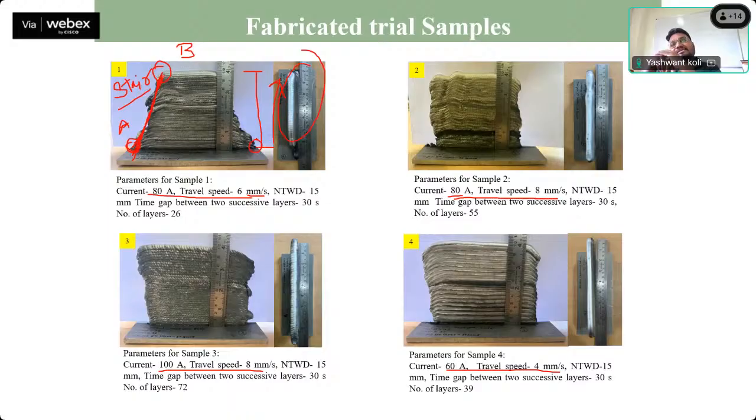This defect can be removed by correcting the dimensional accuracies, at what position the arcing has to be started and the arcing has to be stopped. That consideration we have to take care of. So it should not be like this. This has some staircase defect, you can see, but the undulations are not that much, so after machining the surface will be very smooth.